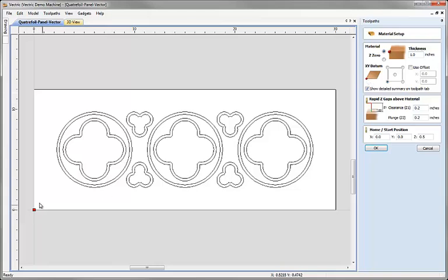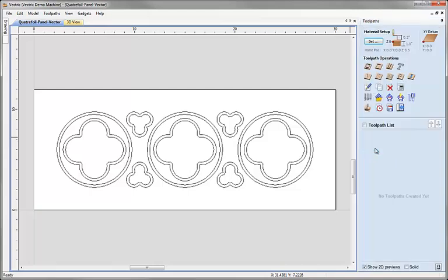I can see in the 2D view the red square showing me that the datum's now in the lower left corner, so that'll be X0, Y0 when we come to set up our parameters for the machining on the CNC. Double check the rapid Z-gaps and the home position are both reasonable for the rest of our setup, and we can hit OK.